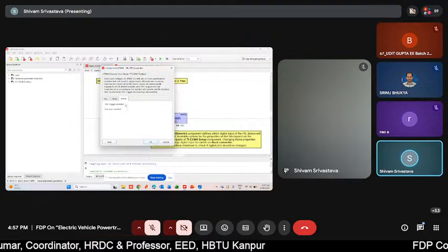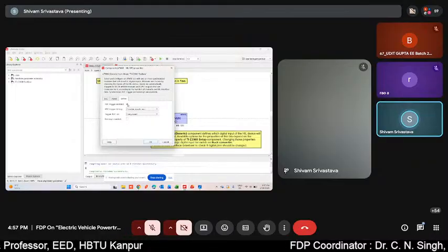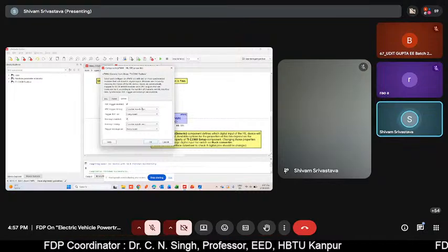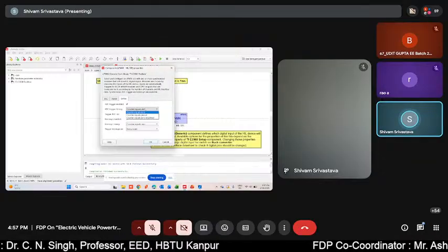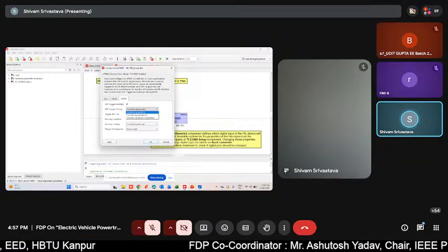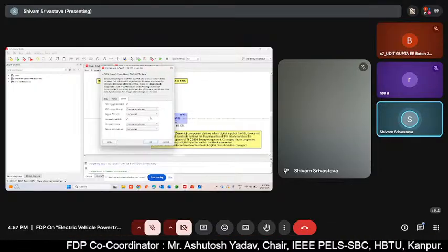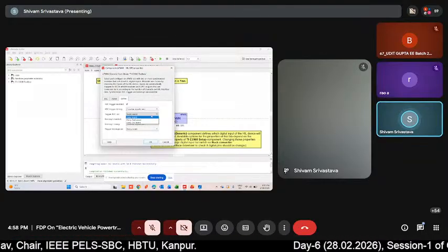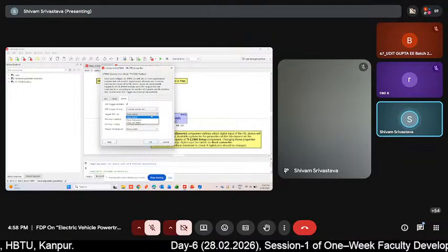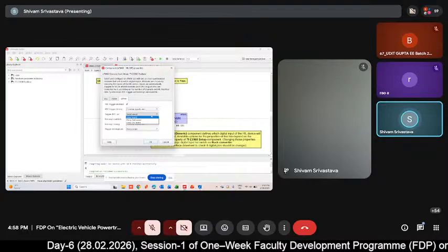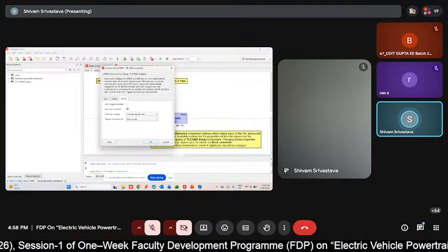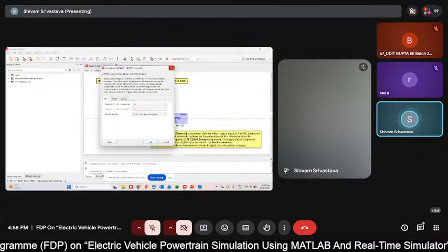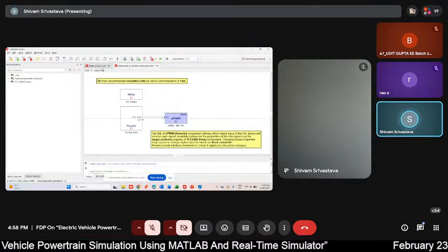Again, you can choose whether you want to enable the ADC trigger, or what happens if you enable the interrupt signal. For the event or timing, whether the counter should be equal to 0, or equal to the period, or equal to 0 or the period. Such scenarios you can apply. You can choose when it should interrupt, or whether the ADC trigger should be on every event, every second event or every third event. It is up to you how deeply you go into these things and analyze them. So these are the kinds of things we can go for.